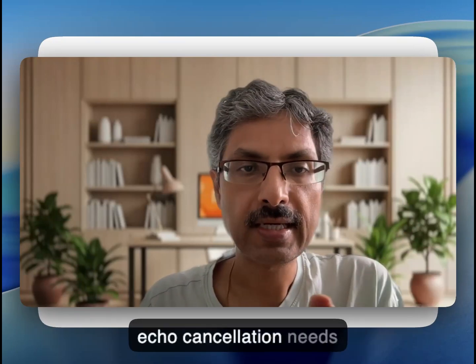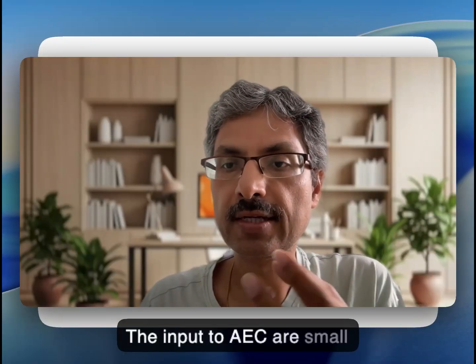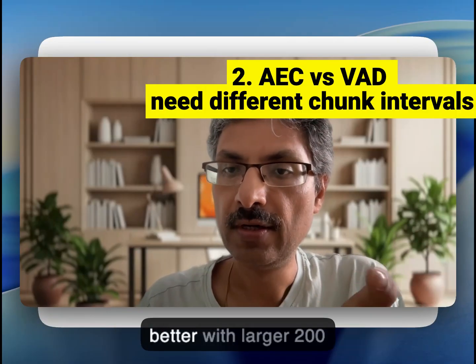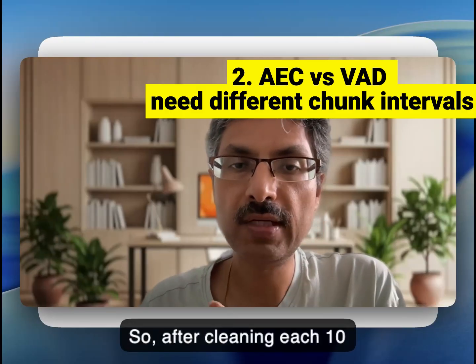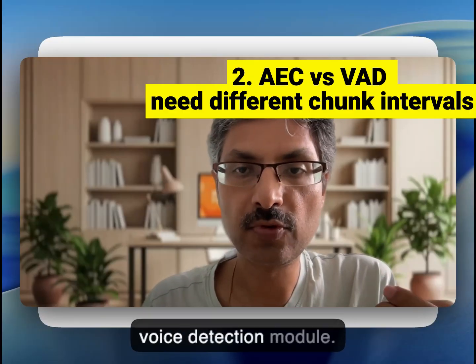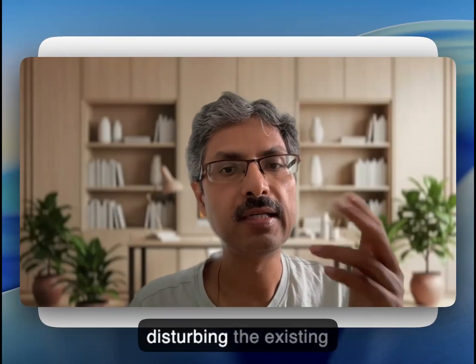Second, the echo cancellation needs small synchronized audio frames. The input to AEC are small 10 millisecond chunks. That gets the AEC working correctly, but then downstream, the voice detector VAD module works better with larger 200 millisecond chunks. So after cleaning each 10 millisecond frame, I collected 20 of them, buffered them into a 200 millisecond window. That was passed to the voice detection module. This kept the AEC responsive without disturbing the existing speech pipeline.